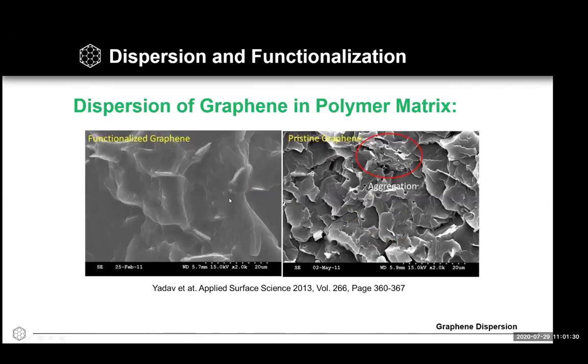The functionalized, optimized graphene dispersion in the matrix remains embedded upon breakage into the polymer matrix, whereas in the material that has not been optimized, where the graphene is not properly incorporated or functionalized for the matrix, the polymer simply breaks away from the graphene platelets, and you don't necessarily get the benefit of the platelets in terms of making a meaningful contribution to your strength.